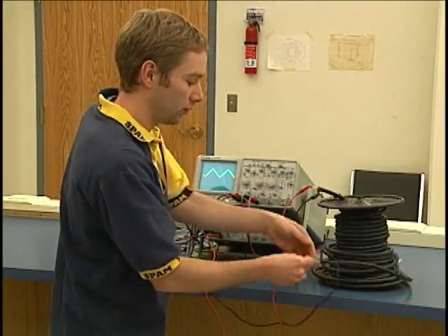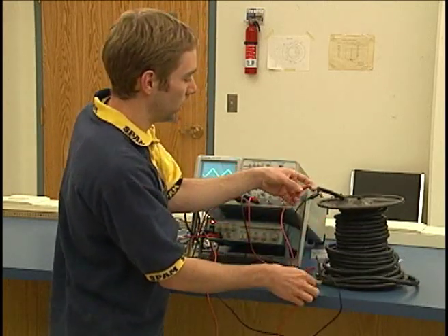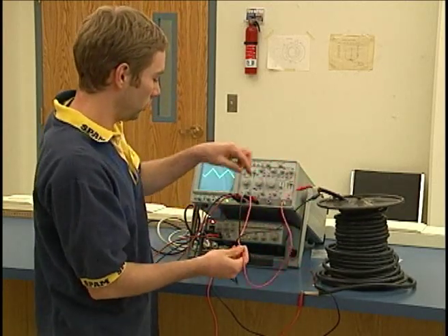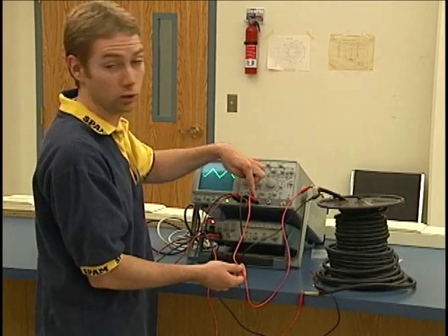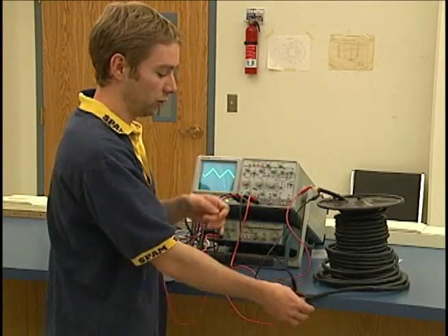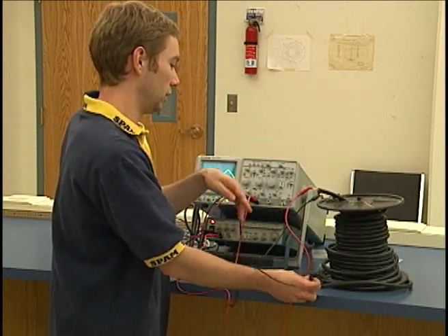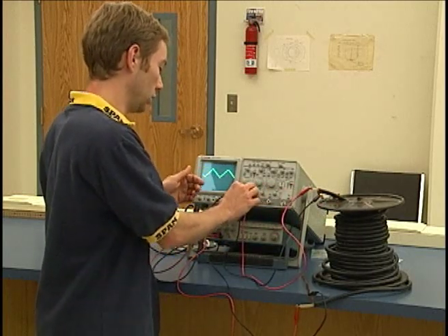On the other side, if you have the red cable hooked up to the inner wire, you want the red cable on the back side going to the inner wire. And what you're just going to do is hook that cable directly up to the red input of channel 2. And likewise for the black one. So if you're putting the black cable on the outside of this, the sheath of this side, you want to have the black one going to the outside sheath on that side and going to your oscilloscope.